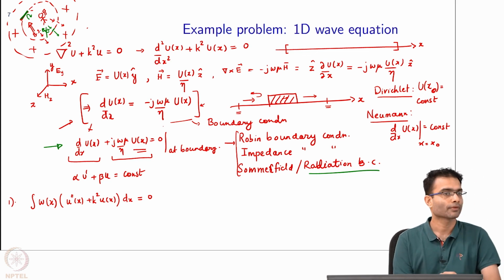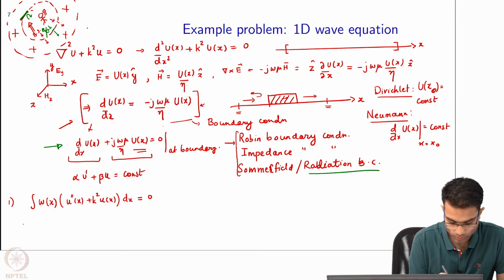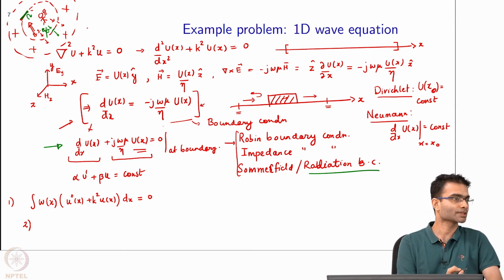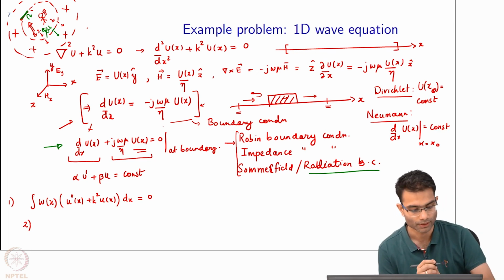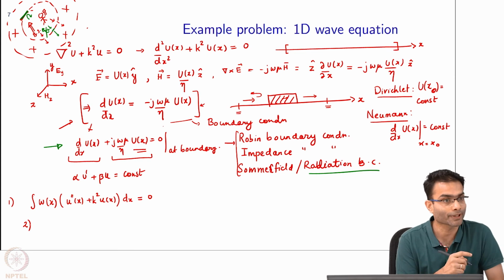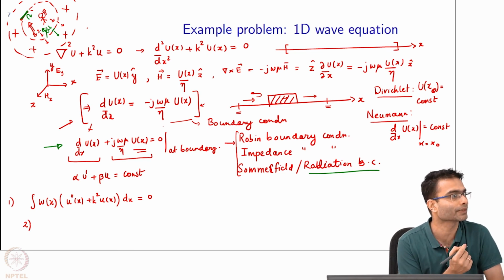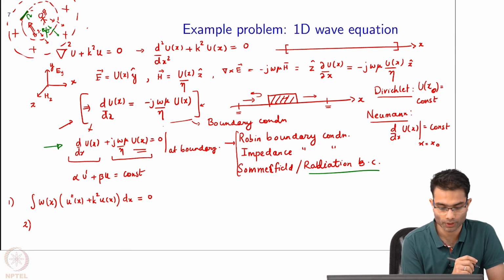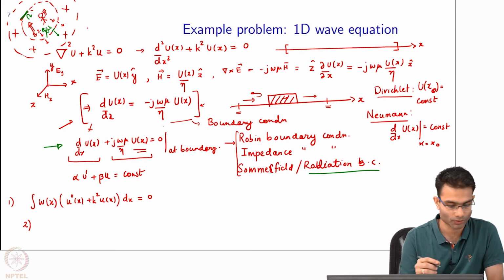I have not yet substituted the basis functions, okay. Next step, step 2, we discussed this previously. What do I do next? Converting to weak form. So, that is basically integration by parts, right. So, what do we do now? There is a double derivative term over there, right. So, that can get converted how? One integration by parts is going to help me with that.